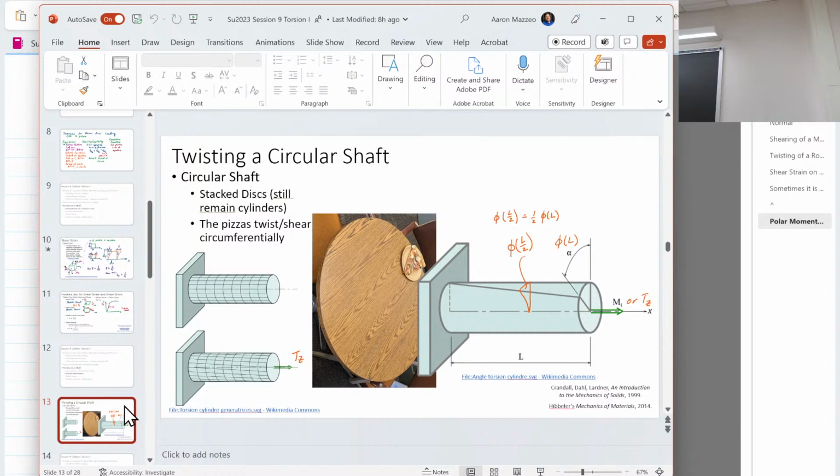So when we do stuff, one of the useful things of the analytical solutions that you'll see in this class is that they are true and you can simulate them as a starter, okay? And so once your simulation matches these analytical results, then you can introduce complexity. But if you just go right to the complexity without doing the simple base cases or the verification models,